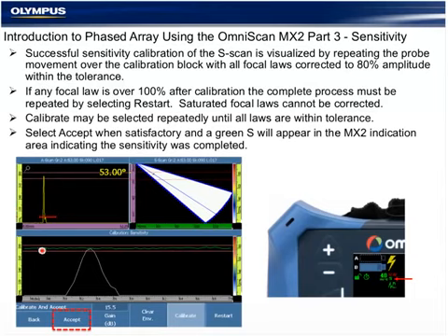It's a very simple math equation the software is performing here, and it must use the same couplant and pressure to be able to complete the repeatability within the tolerance window. So prior to moving to the second option, again, we'll take a quick look at this on the instrument itself.